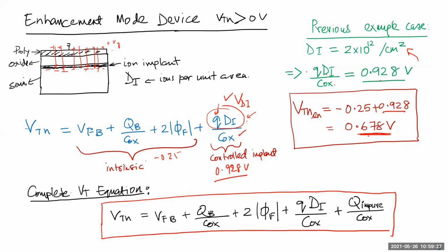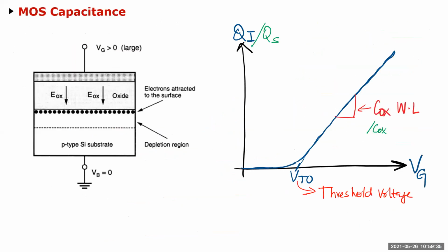For example, if you go to TSMC, IBM, and places like that, they are really the highest quality fabs in the world, so the impurities there are going to be really low. And like I said in the beginning, if you had a depletion mode device, your cap is just going to look like a parallel plate cap. It is going to look like this, and this will be Cox times W over L, whatever is the area of your gate. That is what it would be for your depletion mode.